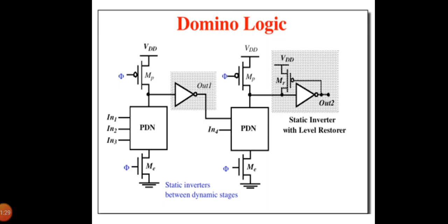So mainly the domino logic avoids the cascading problem which arises in the dynamic block. The cascading problem arises because the outputs of each gate, and thus the inputs to the next stages, are pre-charged to 1, and this may cause inadvertent discharge in the beginning of the evaluation cycle. Setting all the inputs to 0 during pre-charge addresses this concern, and when doing so, all transistors in the pull-down network are turned off after pre-charge. So no discharging of the storage capacitors can occur during evaluation.